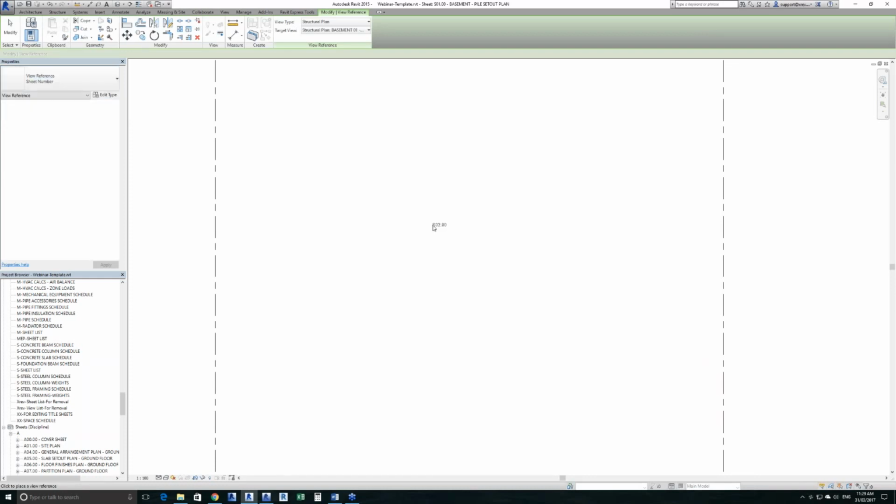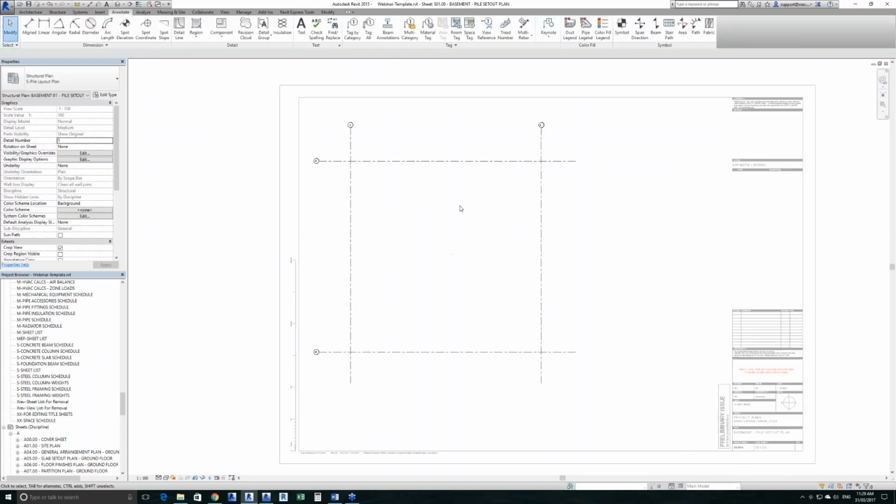So instead of writing in your text note, refer to SO200, you could actually set it up so you go refer to, and leave a space for it and then place this tag in your text note. And that way it's hyperlinked and smart information that links to that particular view. So obviously you can select what type of view you want and what particular view you actually want to use in that particular reference. So that's the point of those ones.